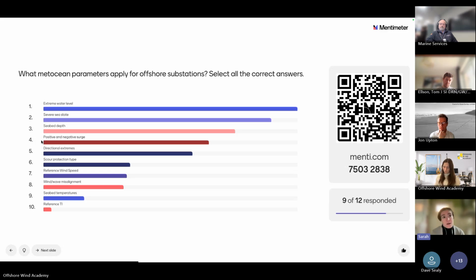A small change in significant wave height, which is the top third of the waves, the height of your waves in the period that you've measured and analyzed, can result in many meters of extrapolated difference in crest height. And there are multiple ways to measure crest height. They are based on two different measurement projects in the Gulf of Mexico during hurricane conditions, and they come up with different results, and one is more suited for certain regions than others. So this is a very sensitive and very important parameter.